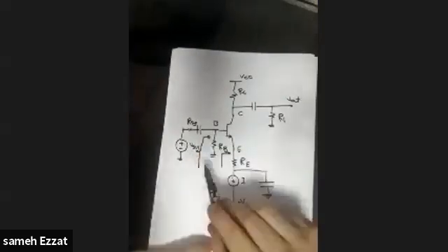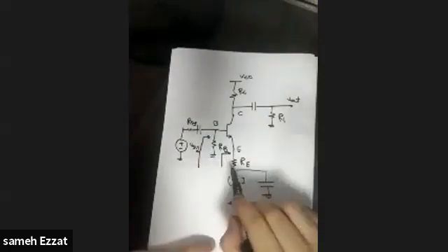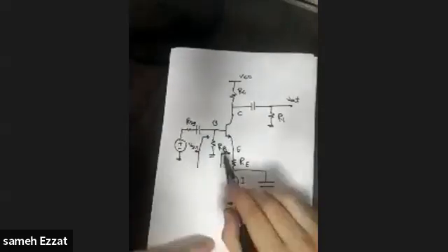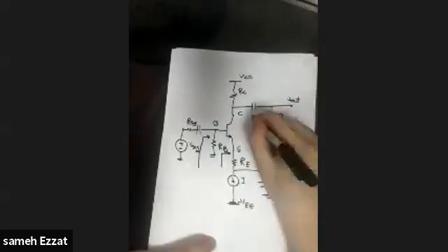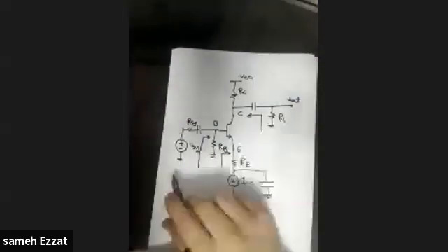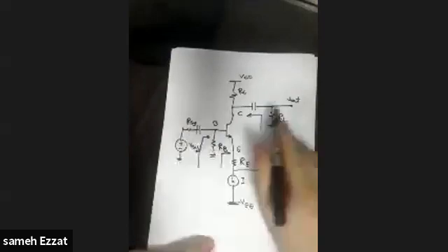So once before and once after the resistance R sig. So we will calculate two input resistances. For the output resistance, the arrow is indicating here. So these arrows are given in the examples. And of course, for the gain, this is V output over V input. This is the relation we are seeking.